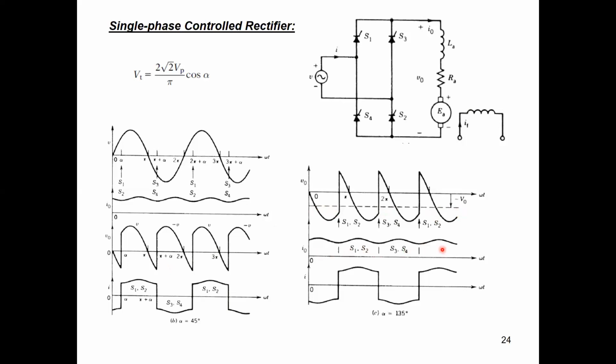The current of the thyristor cannot be reversed. All of time, the current of thyristor moving from anode to cathode. So the output current will be the same, positive. However, the voltage here is negative. If we considered negative voltage multiplied by positive current, this means the power is negative. Power is negative, it means the power is moving from DC side to AC side. So for firing angle equal to 135, the power flow will be reversed from the DC side to AC side.